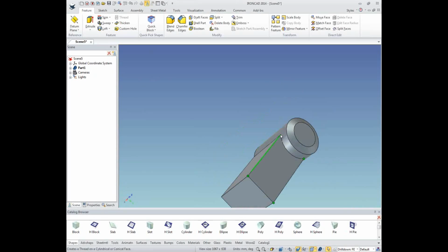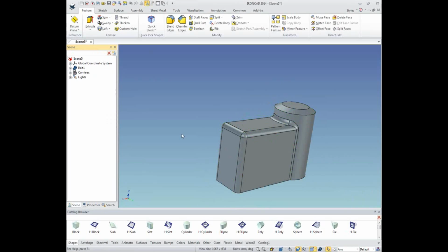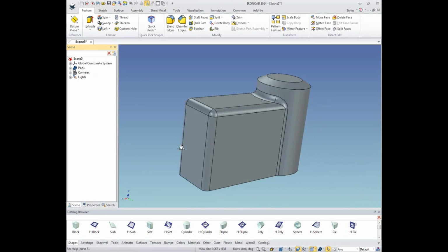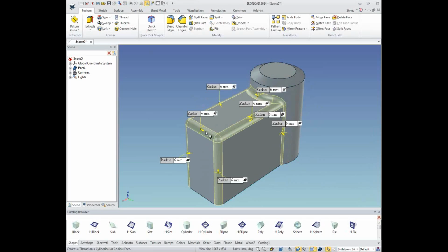And while Kevin's doing that, to apply the chamfer, he simply selected the S key, and that brings up a context-sensitive menu of the commands that you need based on the operation that you're doing. That's right, yeah. And to continue on, once you have a blend set created, you can select it and get these quick tabs for editing individual fillets there.